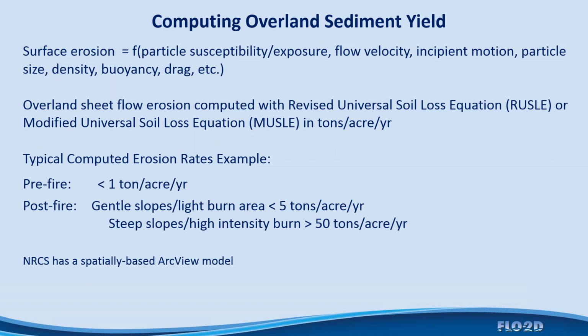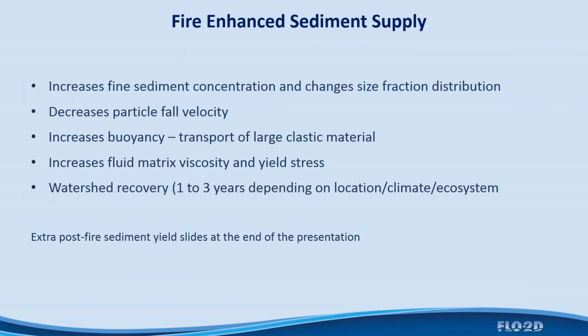I wanted to mention that the Natural Resources Conservation Service, the NRCS, has a spatially based ArcView model that will help you to apply these equations to generate sediment yield. I don't know what the extent of that is, but I suspect that it's on the order of a large portion of the United States at this point. Now, just mention here that fire will enhance the sediment supply for a mudflow event by increasing the fine sediment concentration.